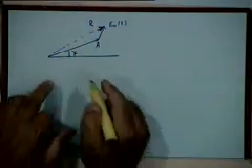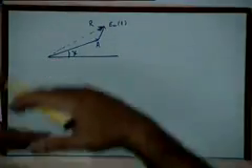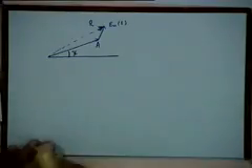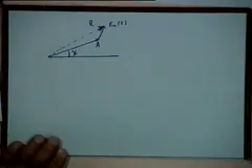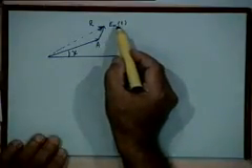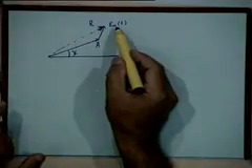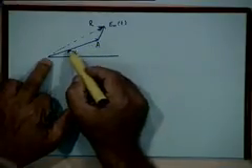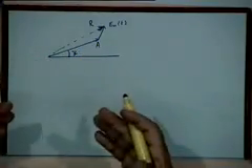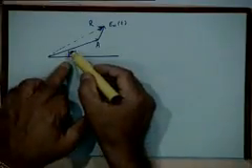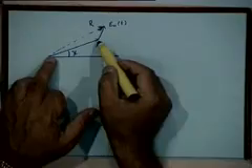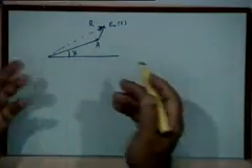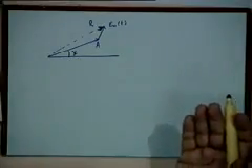Remember this? I am not calling it omega_c t plus psi, because you can assume that the whole reference plane is rotating at a rate of omega_c t. Now notice that E_n(t) is a fast fluctuating phasor, and the carrier phasor, with this angle psi, is slowly fluctuating, because fluctuation in the phase of the carrier phasor will be dictated by the behavior of psi(t), and psi(t) is k_p times m(t).